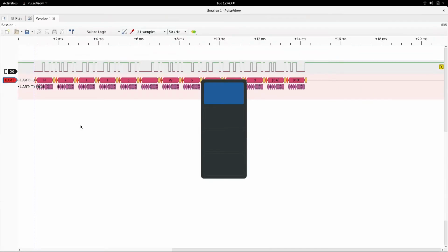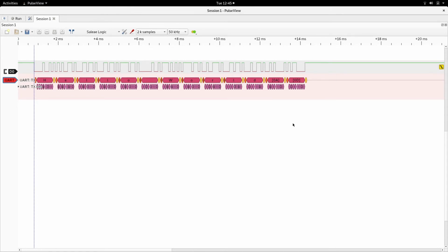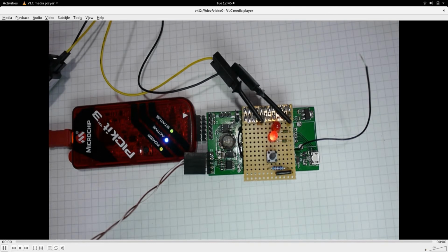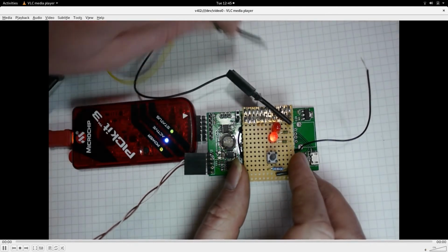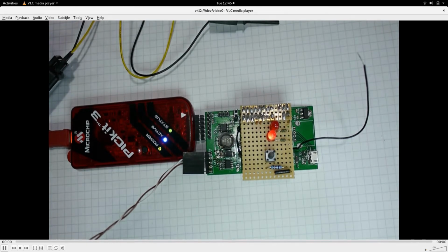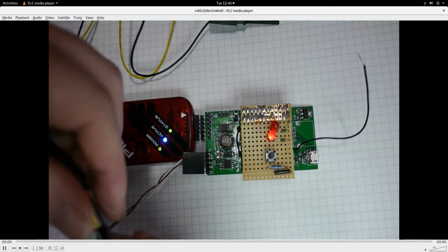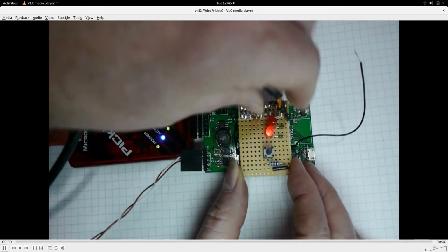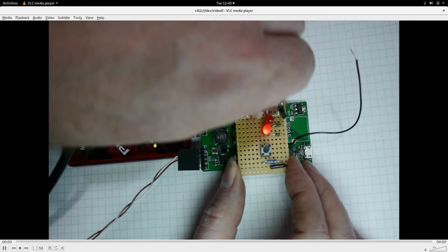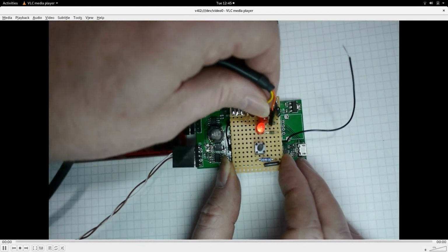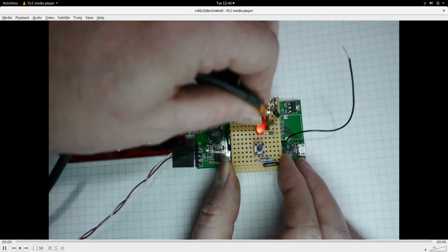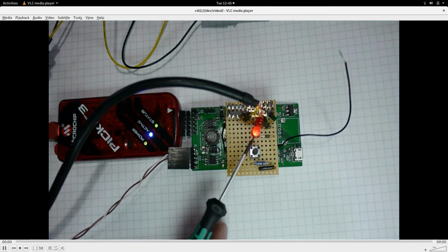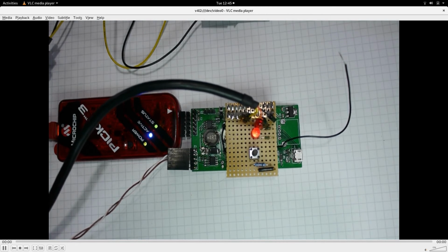Now, the alternative to using Saleae logic is if we just take this and instead of going into a logic analyzer, if we take it into the Raspberry Pi, well, the FTDI Raspberry Pi serial connector cable. So we'll just connect ground, and the yellow is the RX. That LED on D1 was to indicate that our transmit had finished and we'd release the UART again.